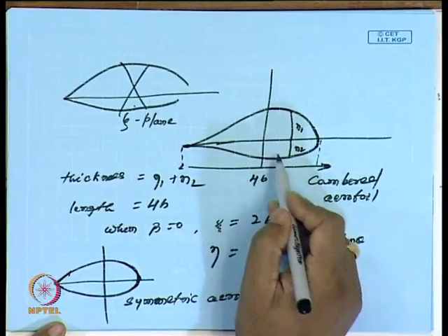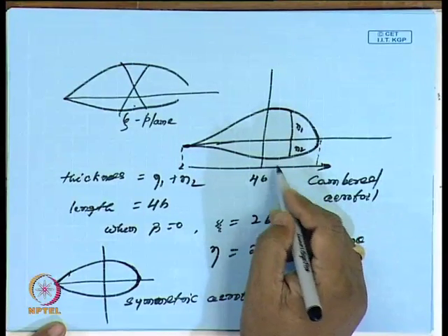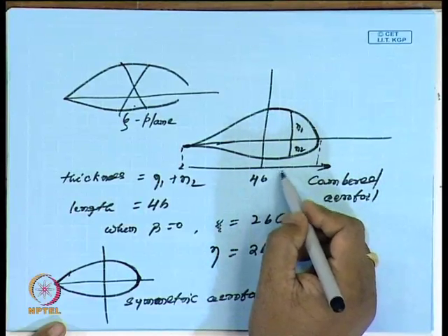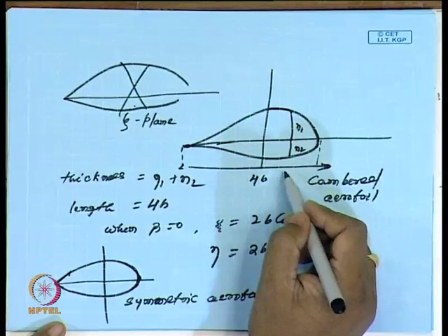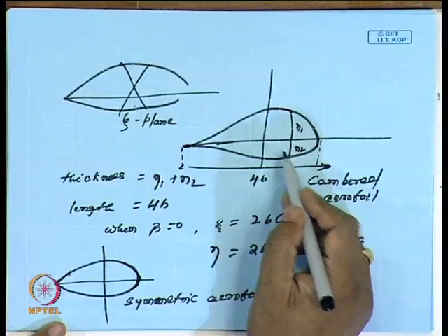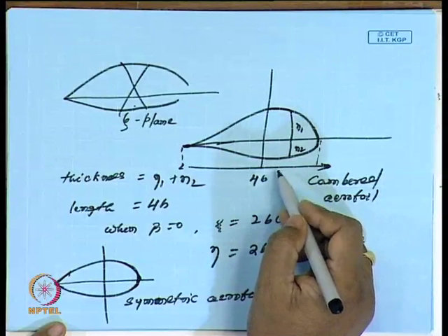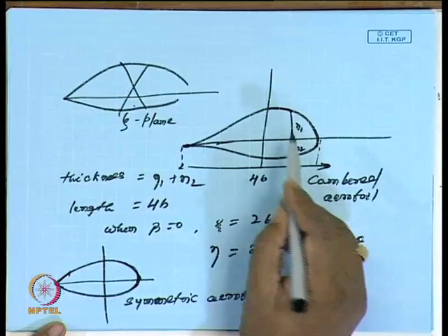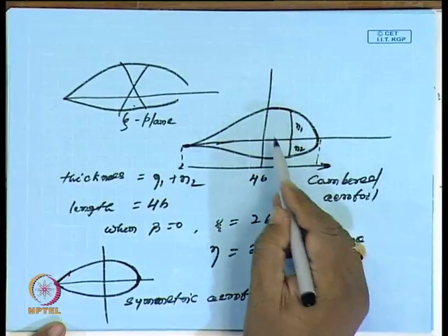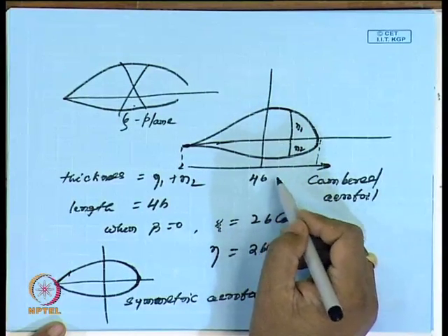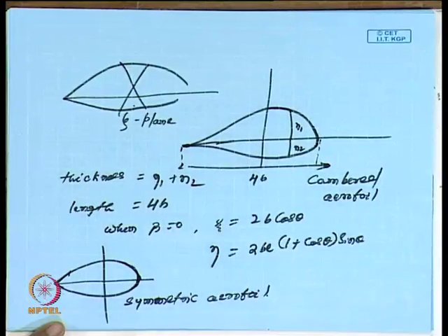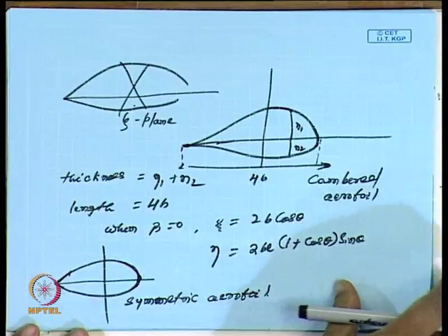Perhaps this is the reason why the maximum pressure is higher on this side. It is one of the reasons why it will act as a lift force, because the pressure is more on this side of the surface compared to the upper surface. So always this will provide an additional pressure thrust, and that will act as a lift force in an aerofoil.